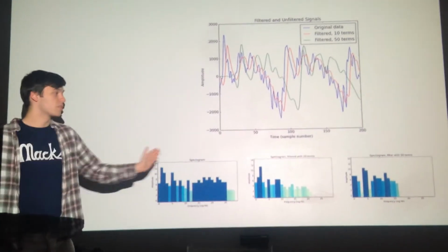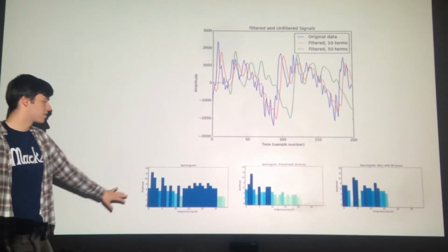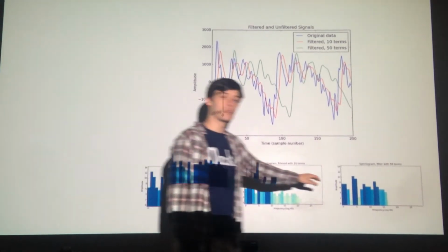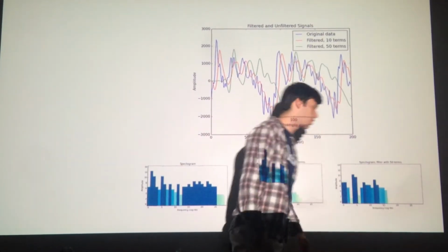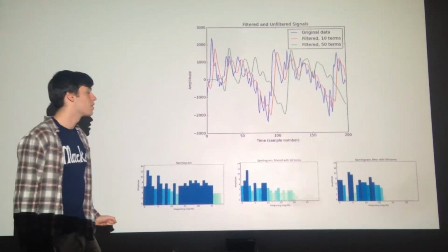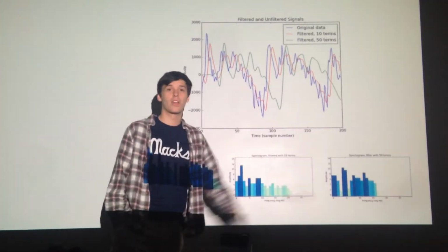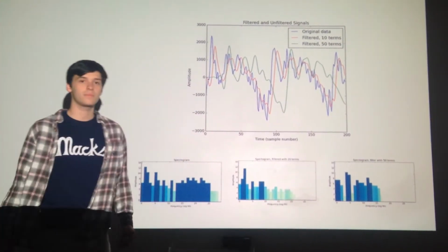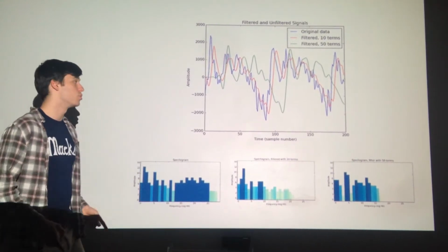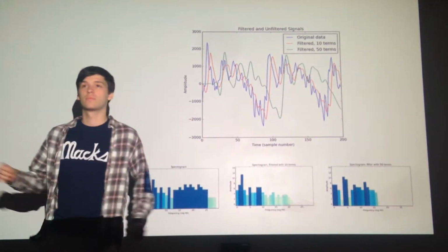So if you look at the spectrum samples that we have as well, you can see that in the normal signal we have a lot of frequencies, whereas in the well-filtered one there's a sharp cutoff at our cutoff frequency, which was 5,000 hertz. With the crappy filter, you see a sloped cutoff, as we expected. We didn't end up using this because we found a better way to do visualization of the beat, which will be explained later.